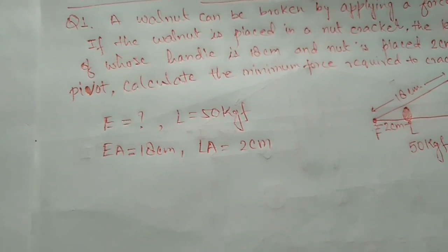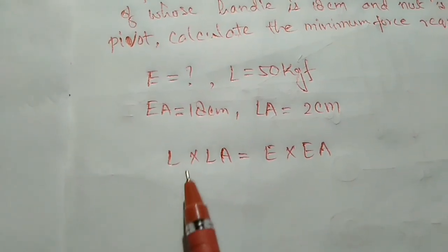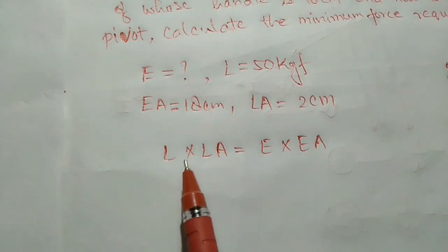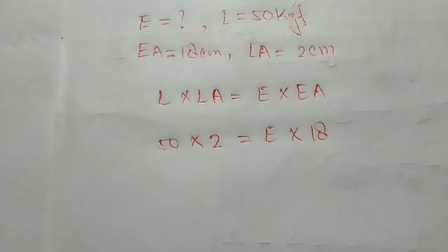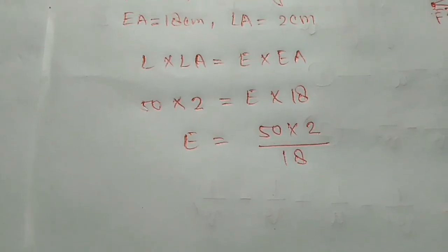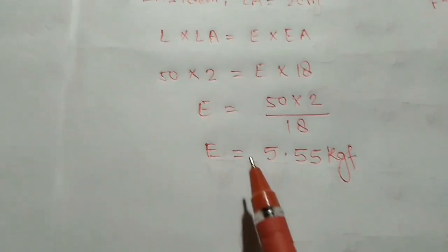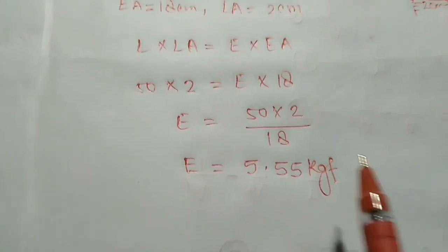Let's write the equation by the principle of lever. By the principle of lever, load into load arm is equal to effort into effort arm. Let's fill in all the values. On solving, the effort comes to 5.55.